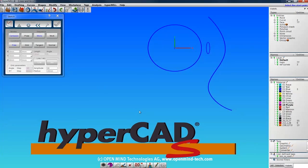The mono sequence will create one line at a time, and the multi-sequence will create a chain. The free constraint allows you to place the endpoint anywhere by clicking or typing in the coordinates. The grid constraint will let you create geometry of incremental lengths and angles based on the step values.